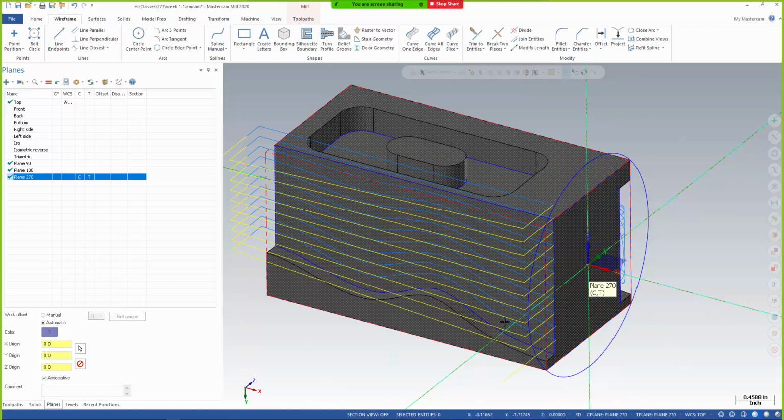I was anticipating to see something specific on the machine through Verify. When I took the program out to the machine and then ran it on the machine, I got a completely different result. Because one of the things that you're going to learn, especially this term, when we talk about 5-axis, and this is going to be one of the things that you're going to have to remember. So you might want to write this down somewhere. On 5-axis machines, there's always two possible solutions.